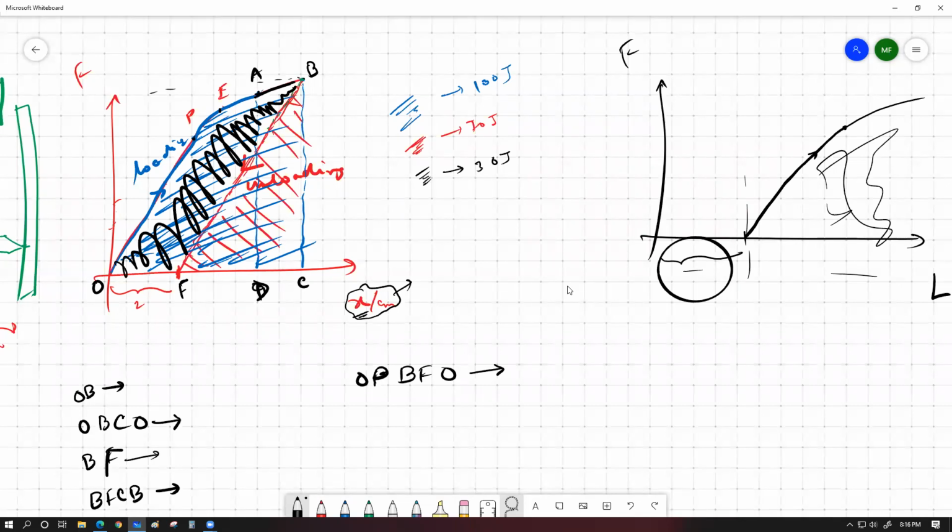I mean, let's say you have a piece of metal. If you are trying to push it really hard without impact load, let's say you are trying to continuously increase it, for example, like a hydraulic press, there is a certain limit beyond which pressing it would become pretty much impossible. I mean, you can theoretically think of an infinite amount of pressure, but it's physically impossible to achieve. So pretty much in all cases, if we are trying to compress a certain specimen, there comes a certain point where a very large amount of increase of force would give us very little deformation.